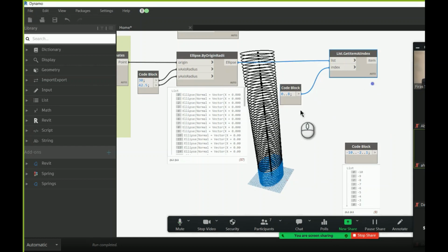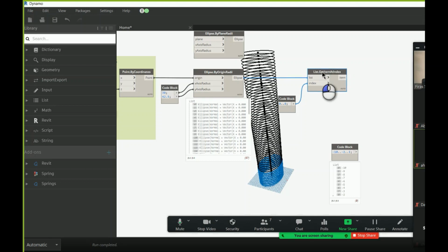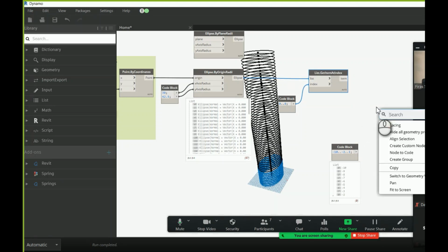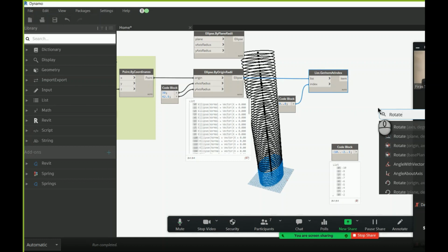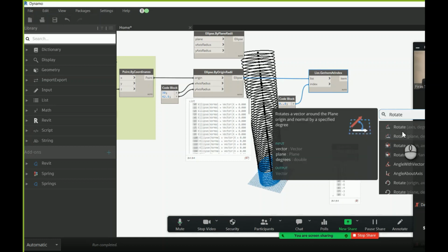That's how it works. Now I know what to rotate, and of course I need to rotate. So what are we going to need? Let's have a look. Be aware: are you rotating a coordinate, a vector, or a geometry? You have to understand whether you are rotating the object or an axis. Read the box on the left. Not this one, not this one. This one. Look at the input. It says geometry.